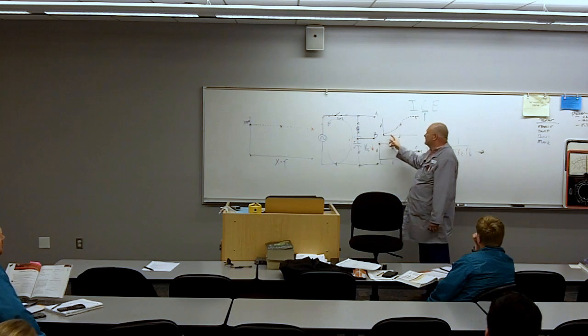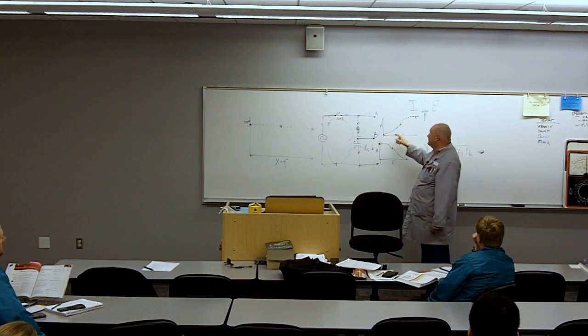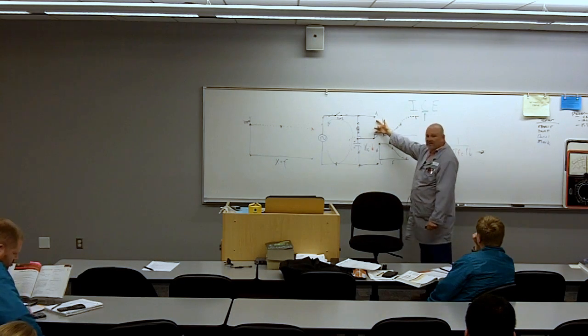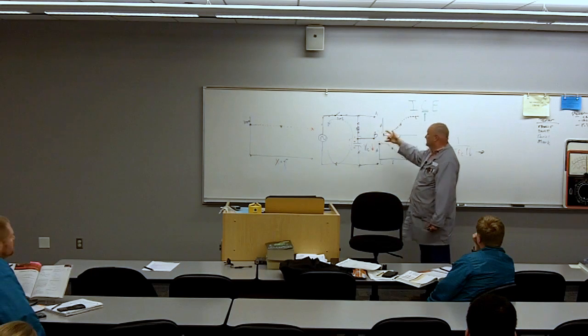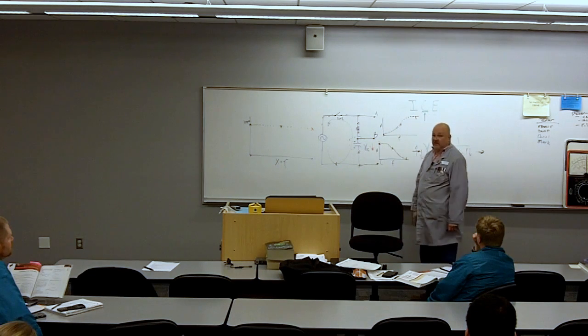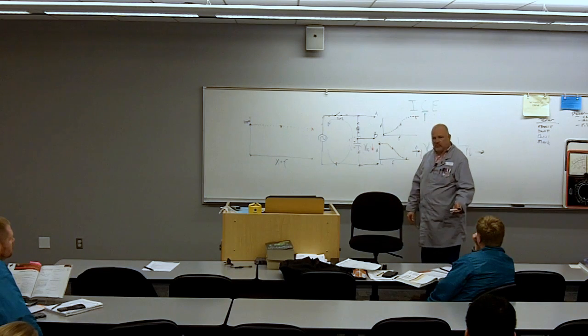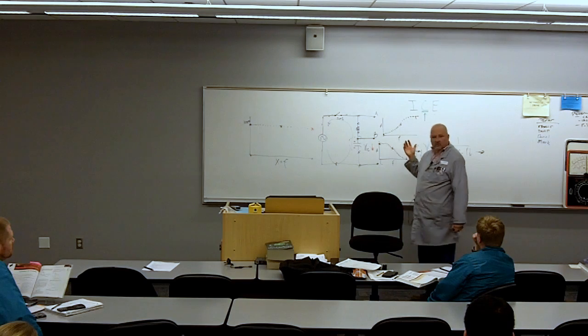So I put a low frequency into this circuit right here. If I'm connected here to this circuit as a high pass filter, I put in a low frequency. That low frequency is not going to make it out. Only the high frequencies are. Some of you have probably heard of crossovers before for speakers. That's exactly what you do. It's exactly what we do.